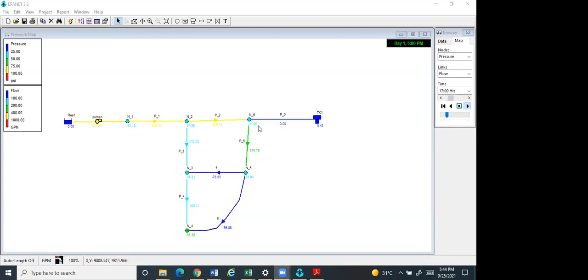You remember that day we had two curves, the inflow curve and the outflow curve. When we take the maximum difference between the inflow and the outflow, we had a value that day of 15 cubic meter and 170 cubic meter. So that is the equalization volume.